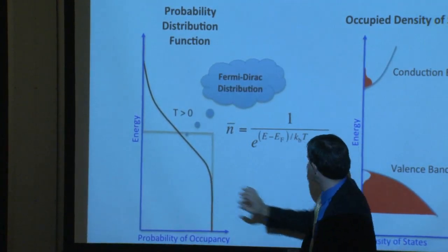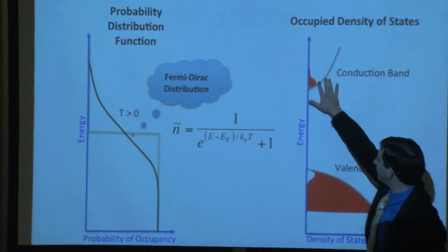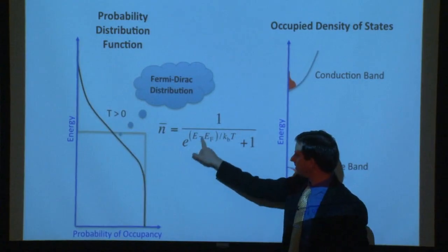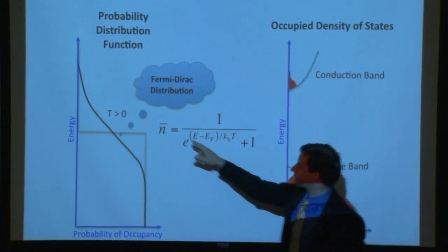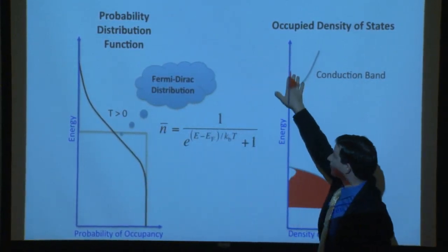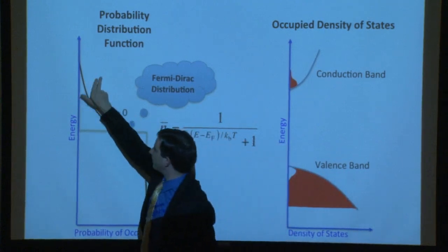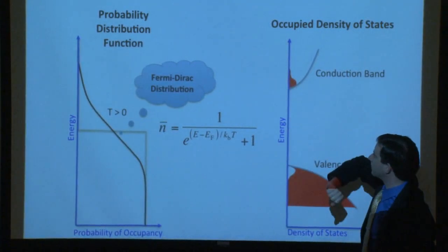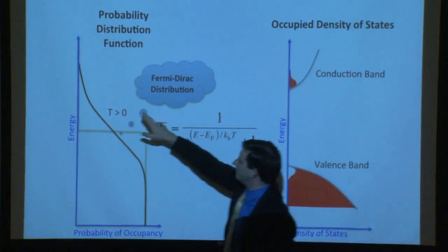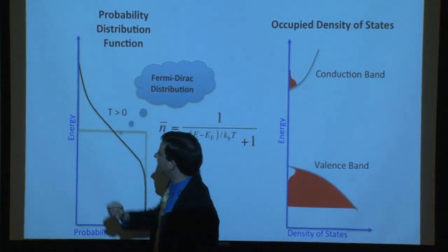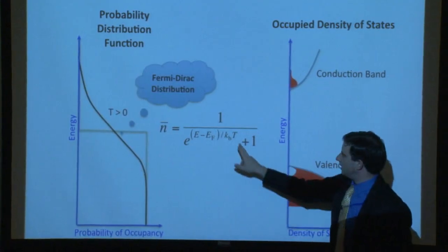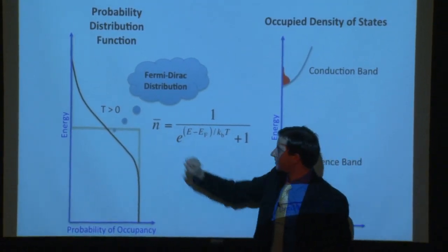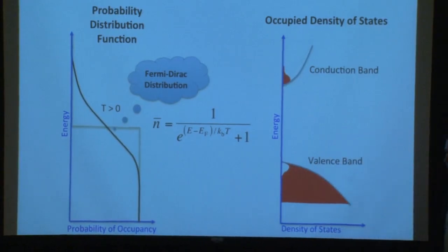What that means is the density of free carriers will increase with temperature. And because of the Arrhenius dependence here, we have an exponential increase of the number of free carriers with temperature. Because the function right around this region, which impacts the electron concentration in the conduction band, this small portion of the Fermi-Dirac equation can be approximated by an exponential. If we have an increasing temperature, we should have a drastically increasing carrier density. And let's see if that's indeed the case.